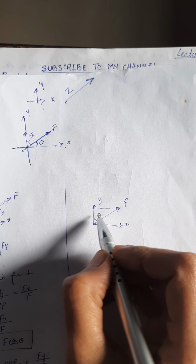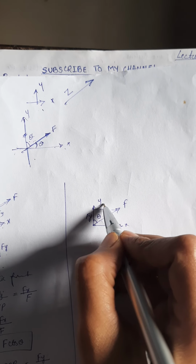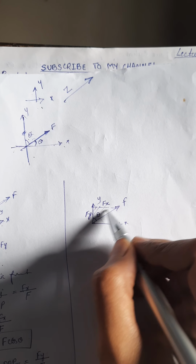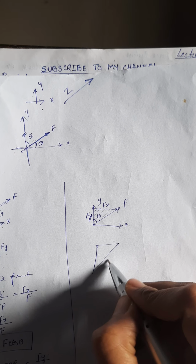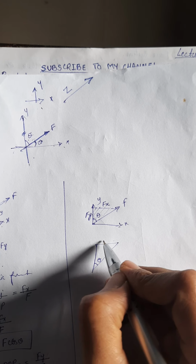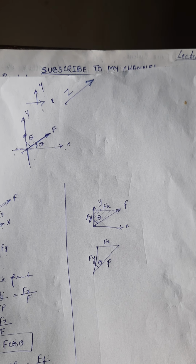As we have drawn this perpendicular, this vertical will be equal to F of y, and the horizontal will be equal to F of x. Now just consider this right angle triangle. It is something like this. This is our force F. We have theta here. This is F of x and this side is F of y.